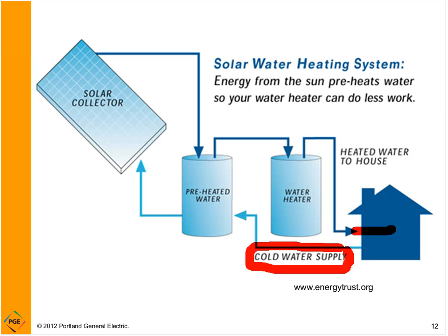If you can preheat the water in a preheater tank with your solar collector, all the energy that comes out of the solar collector can go into that water. Basically, it can do that because the temperature difference between what comes out of the solar collector and what goes into the solar collector is pretty big.